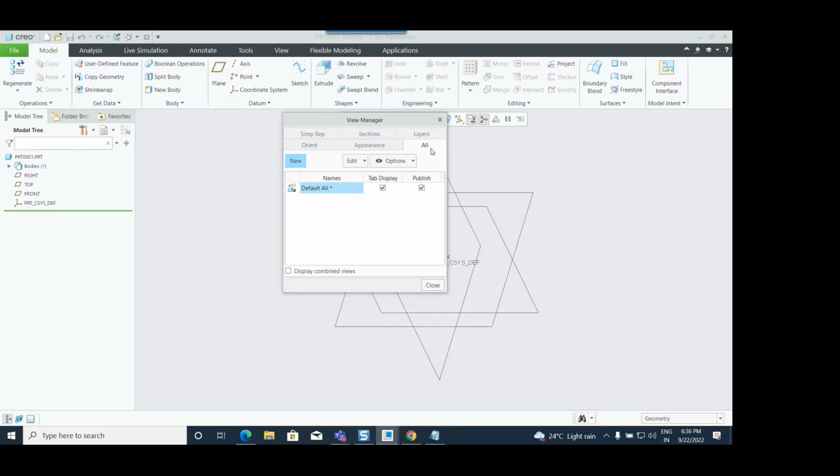all of their information in the All tab. In the All tab, I can combine the information coming from the remaining 5 tabs. Whatever I define in the All tab is called a combined state. That is the very basic definition or theory of a combined state. By creating different combined states and organizing the information into them with the help of data coming from other tabs, I can create different views and orientations, show some information and hide the rest. That is the approach towards MBD using combined states.